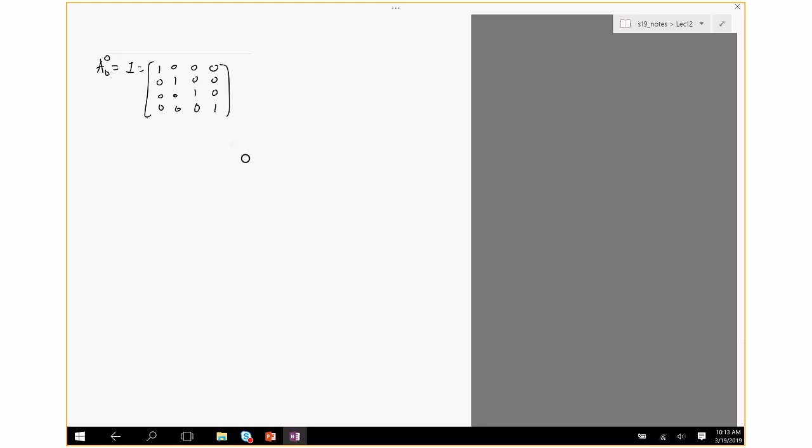A10 comes from the formula for the DH, and you can do it by hand, or I would recommend using MATLAB, the symbolic toolbox. This is cosine 1, sine 1, 0, 0, minus S1, C1, 0, 0, 0, 0, 1, 0, 0, 0, D1, 0.